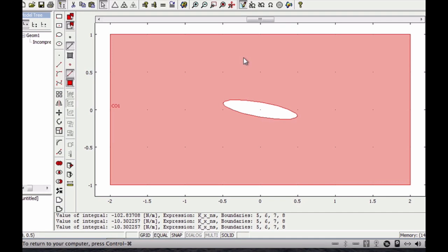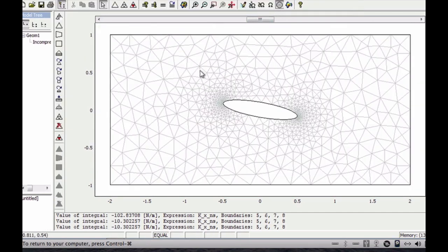Yeah, okay, so this is an airfoil. We made the point last time that this is a model called a finite element model. It divides the whole body up into a whole series of little triangles. And for each of these triangles, you could think of each of these triangles as basically a Reynolds transport theorem domain, a free body domain, in which we're solving for conservation of momentum in x, in y, and mass in equals mass flow out, conservation of mass. So we have 3 equations for each of these elements.